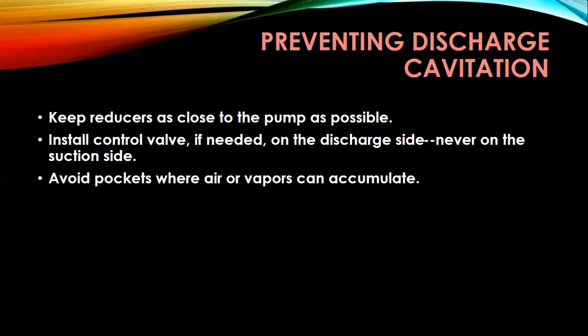How can we prevent discharge cavitation? Keep the reducers as close to the pump as possible and install a control valve if needed on the discharge side, never on the suction side. Avoid pockets where air or vapors can accumulate.